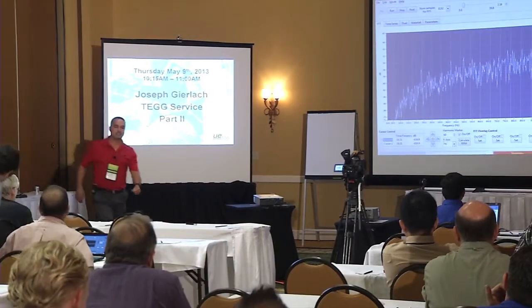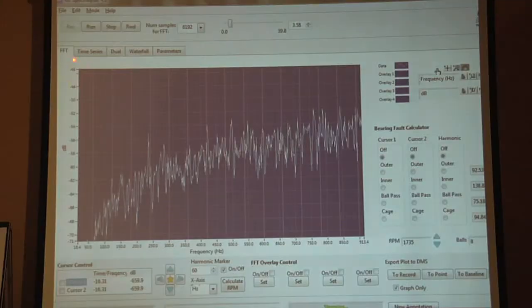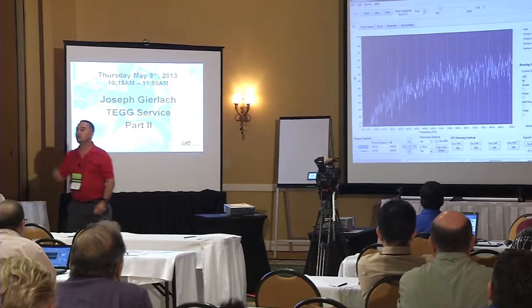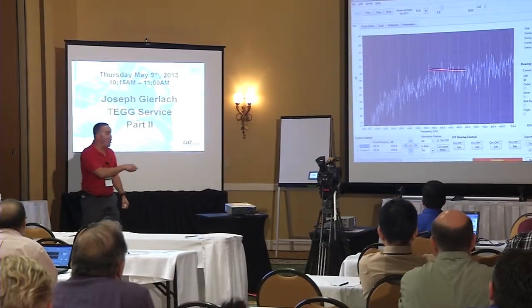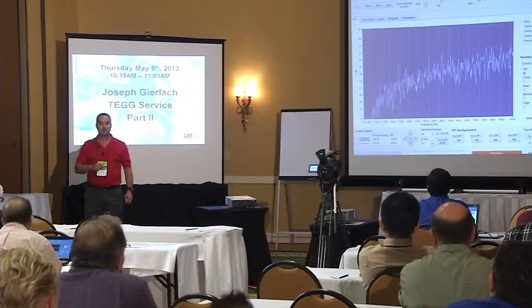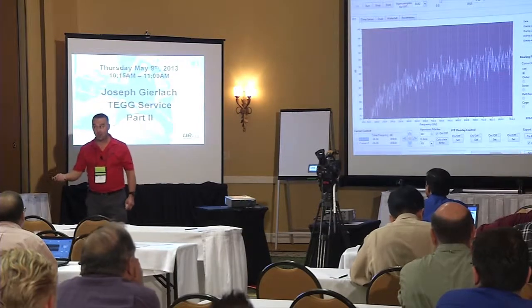What does the frequency spectrum tell us? The way I have this set up right now, my relative scales from -45 to -71, and I'm still out to about 913 hertz on the bottom axis. And this is the view I get with the 60 hertz marker on. What can we see in this view? Some that are on the harmonic, not all of them, right? But we do agree we have some, right? And what else? We got a lot of noise in here. That tells us what? It is electrical, right?